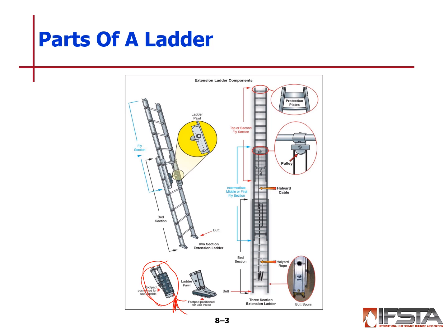And then right here, this is known as the dogs or locks. The locking mechanism, as the ladder or the fly section raises, it clicks and locks in. In order to disengage it, you have to pull it up past the closest rung to it, unlock it, and then let it back down.